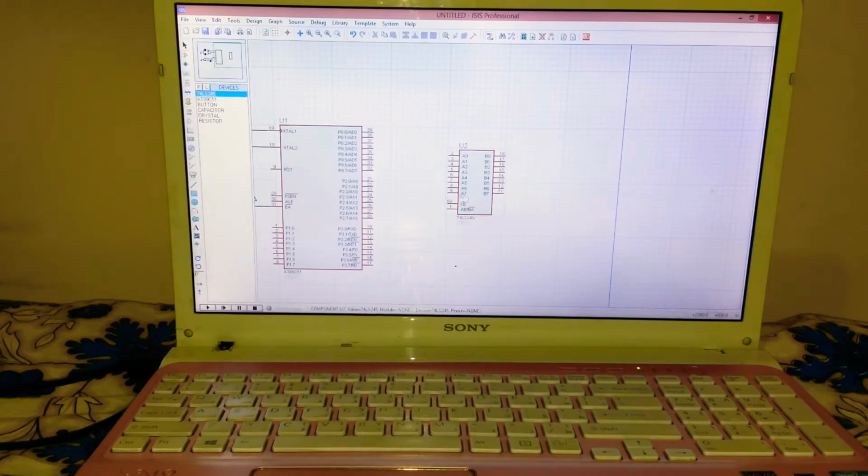So connect the port 2.0 to 2.7 to this 2, 3, 4, 5, 6, 7, 8, 9 pins of the 74LS245 IC. So start connecting here. We'll go step by step so that you won't be confused at all. So I'm just connecting all of the stuff here. Later we'll be taking the 7-segment display into the picture very soon after we connect all the pins. So the last two left, here we go. So the last one, here we go.